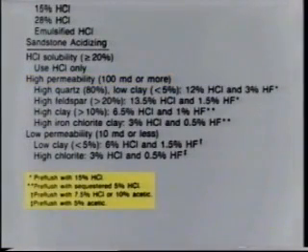The recommended pre-flush fluid is extremely important and will prevent or reduce formation damage caused by harmful precipitates. In reservoirs with low permeability, 10 millidarcies or less, HCl concentrations need not exceed 6%, and HF concentrations 1.5%. Tests have shown that very low permeability sandstones, about 0.5 millidarcies, with a high clay content may require an HF concentration of only 0.5% to avoid damaging the formation.